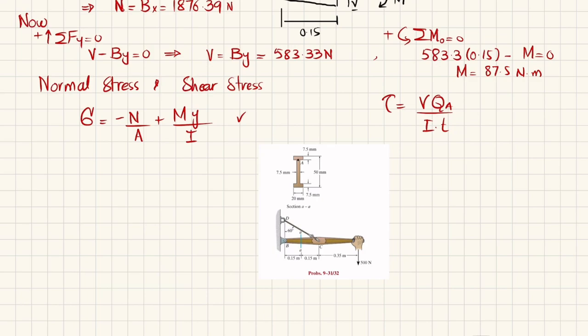If we take the whole as a rectangular box having dimensions 20 by 50, and then subtract these two portions, we will get the area of this I beam. Clear? So I will write it: the area will be equal to this width, which is 20 millimeter, so in meter it is 0.02 meter, and the height is 50 millimeters, so 0.05, minus this height.